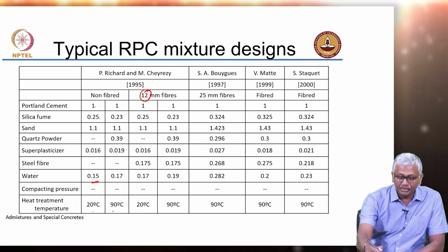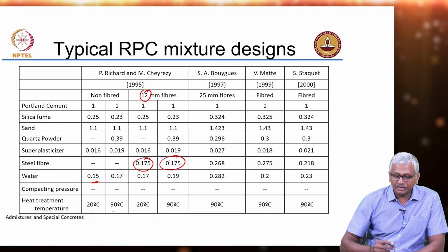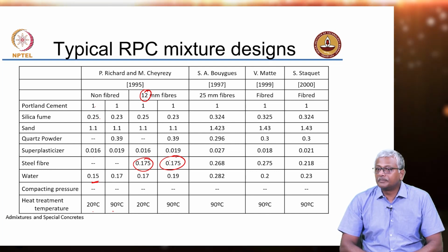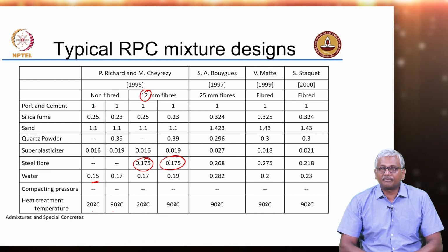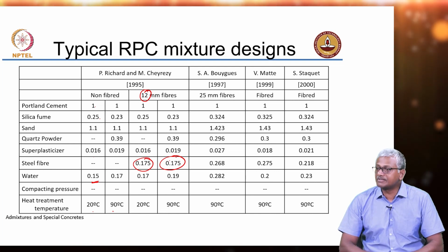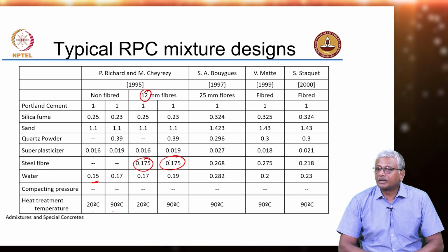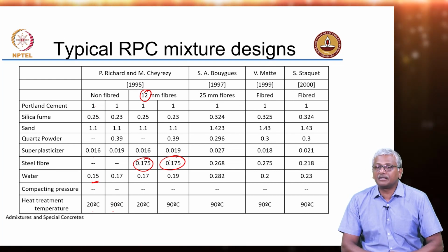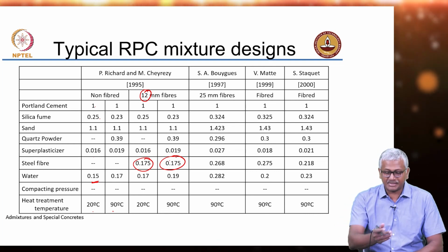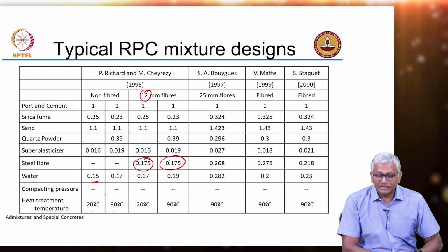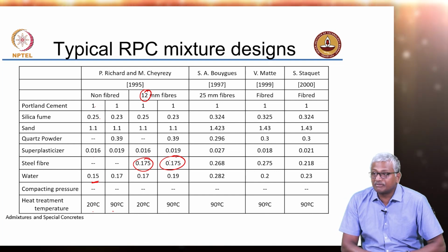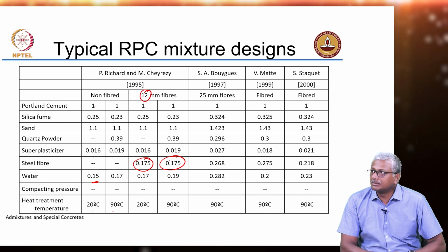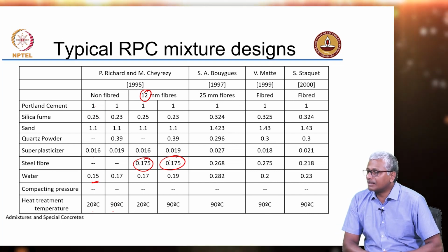As you can see, the fiber dosage was significant, 0.175, per 1 kilogram of cement you have 175 grams of fiber. That is a fairly high dosage, okay. Considering there are about 800 kilograms of cement in the concrete in this case, right. So, imagine you need to multiply this 0.175 by 800, how much does that become? 17, 8, let us say 150 kilograms.